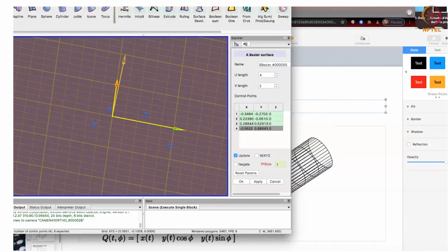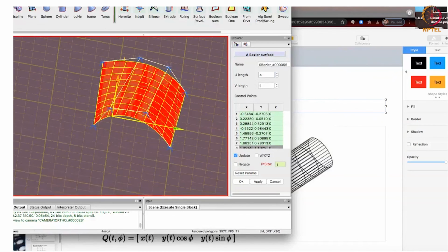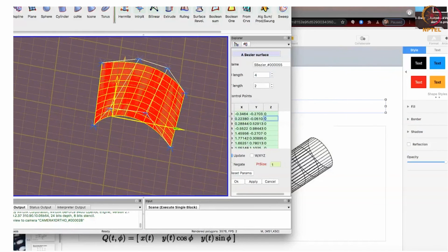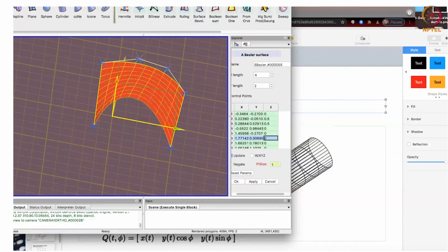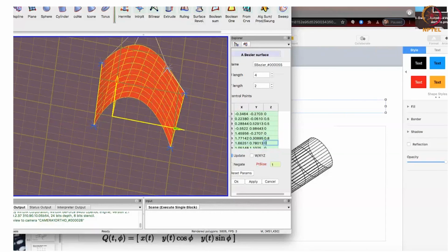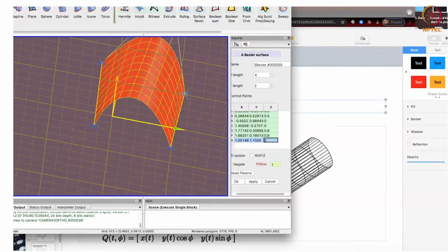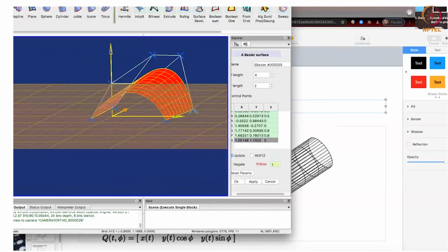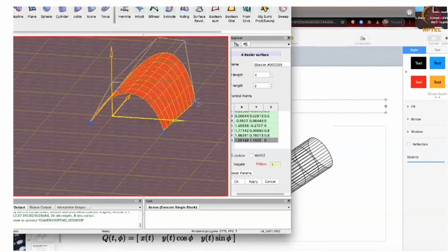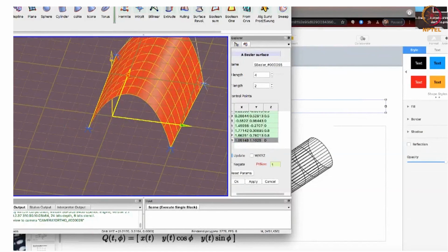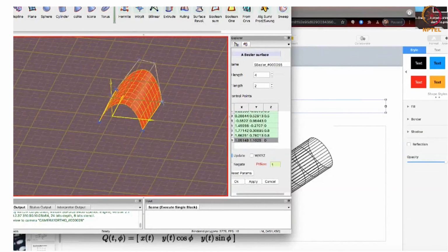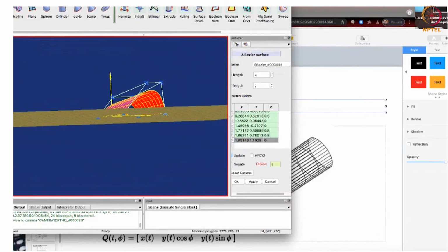I'm going to repeat this again. You can see this is a Bezier surface, but all on the same plane, so I'm going to elevate this a little bit, maybe 0.8 or whatever. You can see a Bezier surface here. How many control points are there in this particular case? Are you guys seeing my picture here? What is the control net size here?